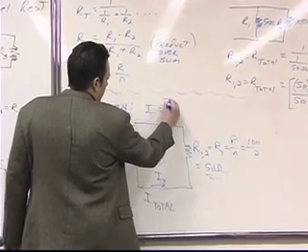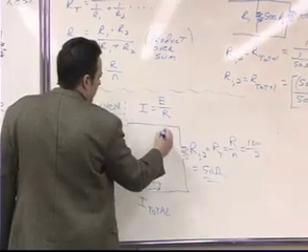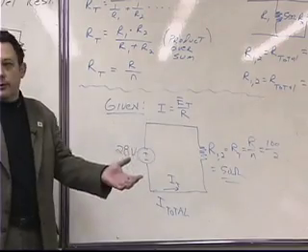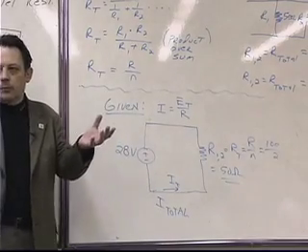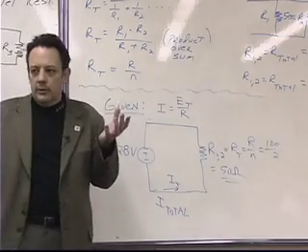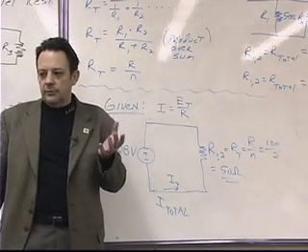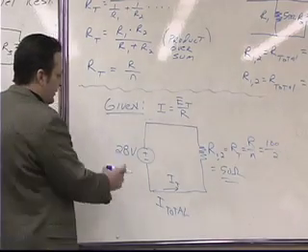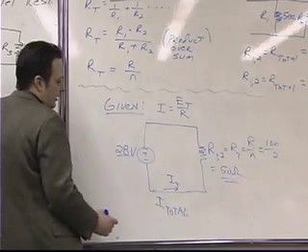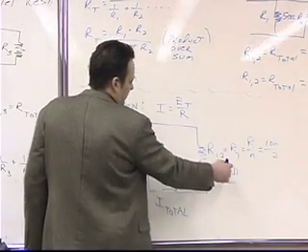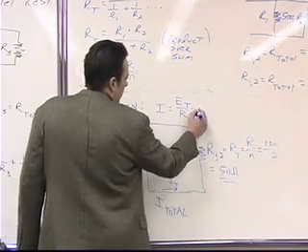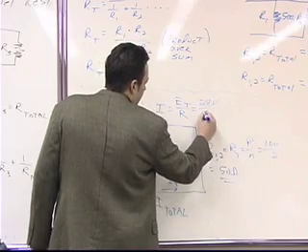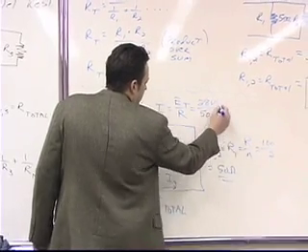We've seen this many times. Current is equal to voltage divided by resistance. We're talking about the total voltage. So if there's multiple batteries, we've got to basically break those down into one equivalent electrical pressure or one equivalent electrostatic potential difference, okay? Or one equivalent battery. And in this case, ours is 28 volts. And then our total resistance was 50 ohms. And so our current is going to be 28 volts divided by 50 ohms, which is equal to what?